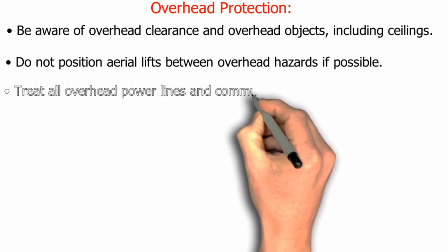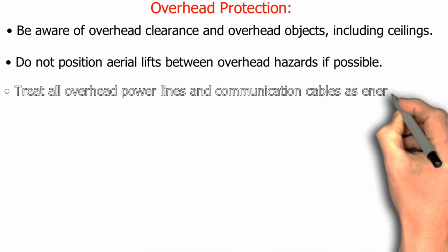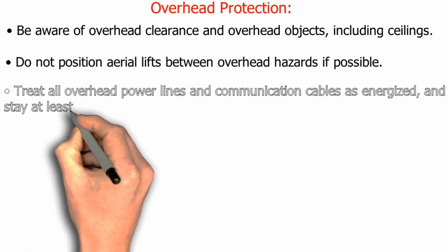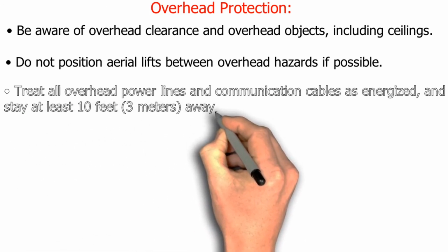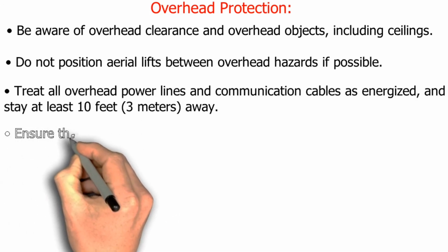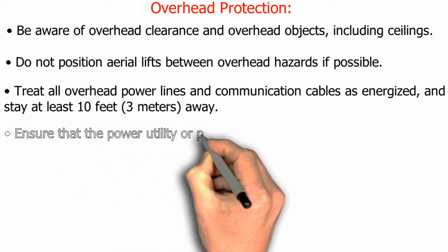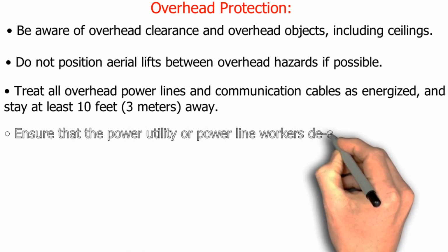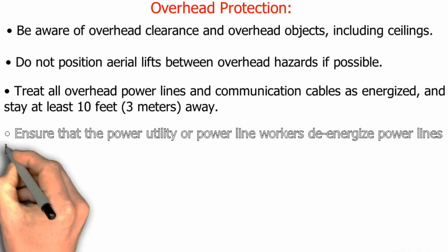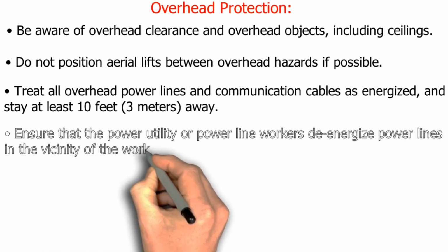Treat all overhead power lines and communication cables as energized, and stay at least 10 feet, 3 meters, away. Ensure that the power utility or power line workers do not energize power lines in the vicinity of the work.